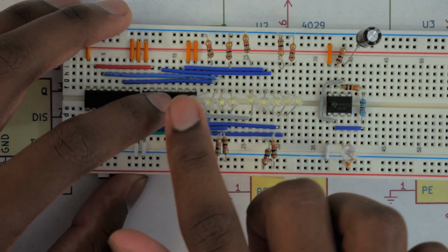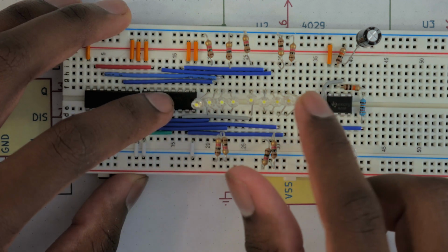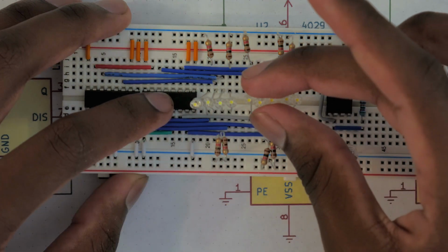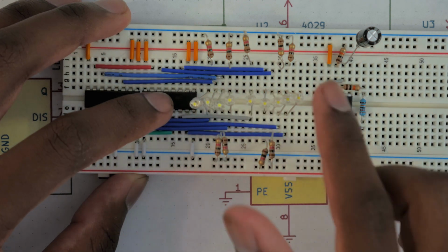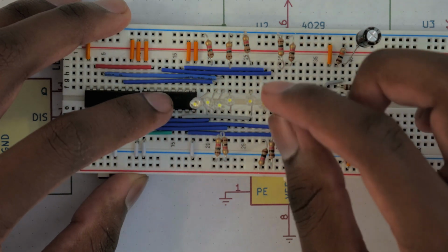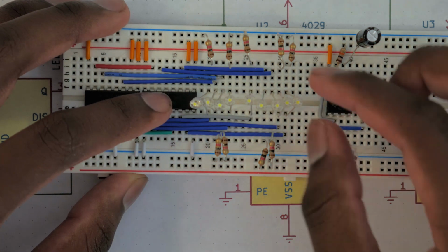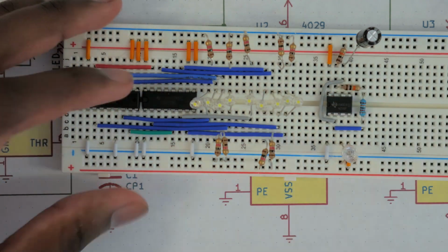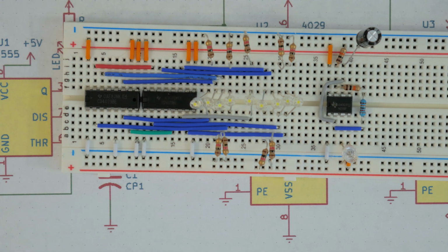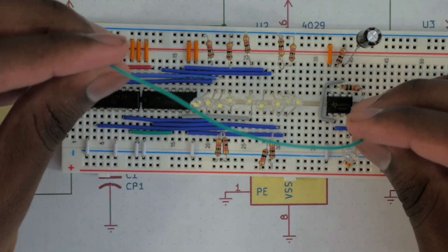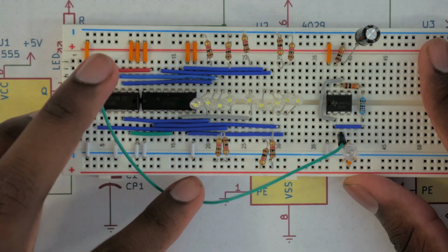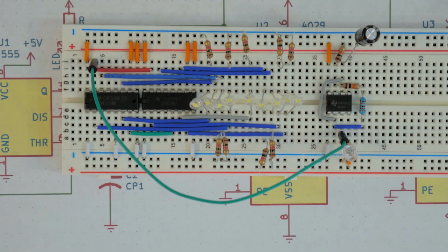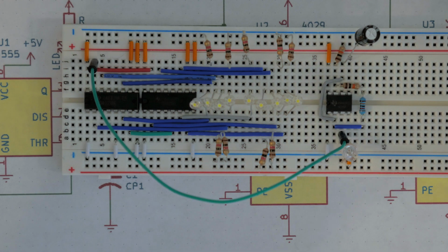So this corresponds to the first digit, and this will correspond to the 8th digit. Or is there 9? I think this is maybe the carry out, because we got 4 here and we got 5 here. So this is the carry out of the last one, our 9th bit. Now remember, this carry out is going to be inverted. I don't have a line that connects the clock to the clock, so we take the clock of our 555 timer and connect that to the input clock here of our 4029. Get power connected here.